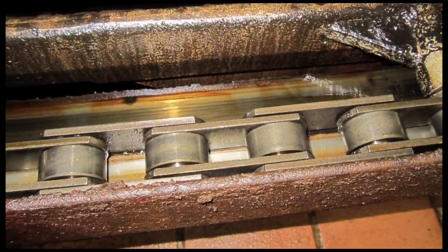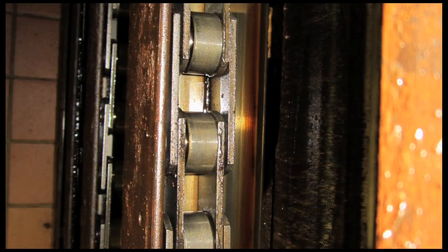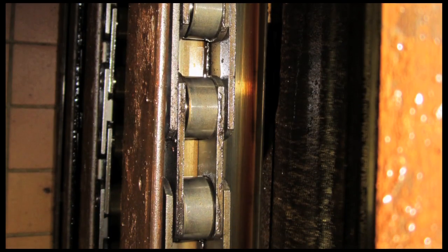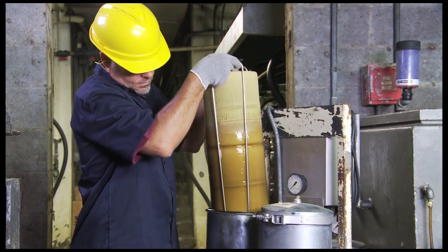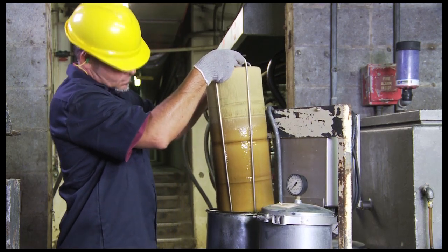Oil does more than reduce friction and dissipate heat. Lubricants also help to prevent contaminants from depositing on the surface, so they reduce buildup or sludge. The lubricant washes away the contaminant to a filter where the material can be removed. As shown in this salt fog corrosion test, lubricants also help to protect against rust and corrosion through chemical additives.